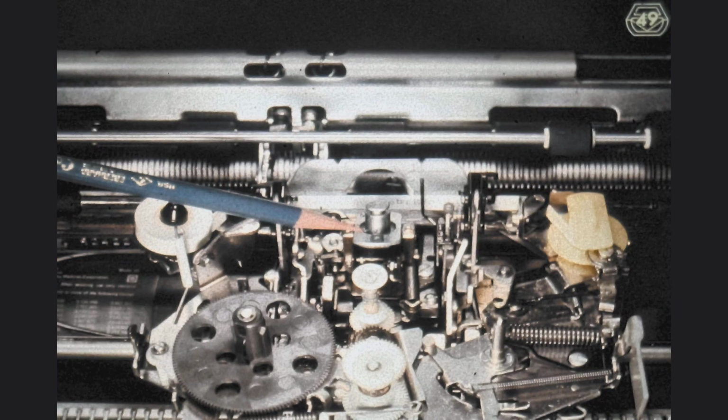During the reinstallation process, we approximate the correct positioning of the type element by pointing the indicated pin on the upper ball socket in the 7 o'clock direction, as shown here. Actually, this positioning of the pin, which locks the element onto the upper ball socket, is completely immaterial until we have performed the rotate tape adjustments. We will study the rotate tape adjustments in Learning Program number 10-4B.